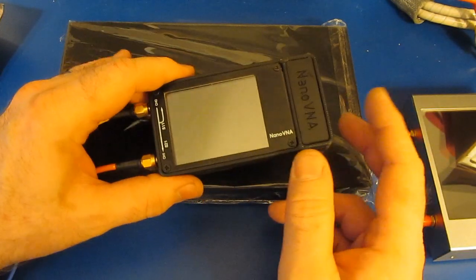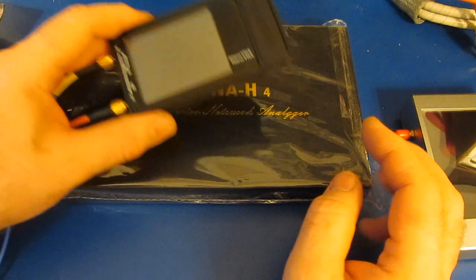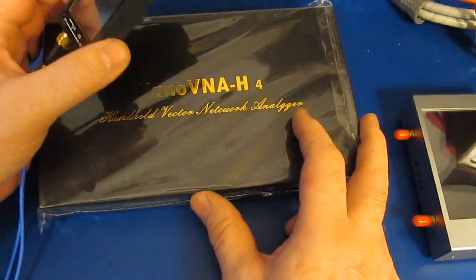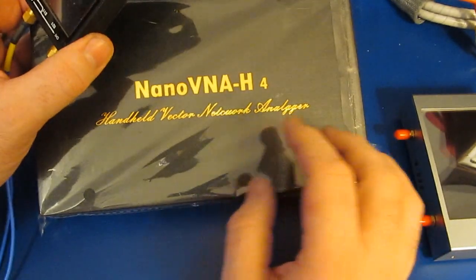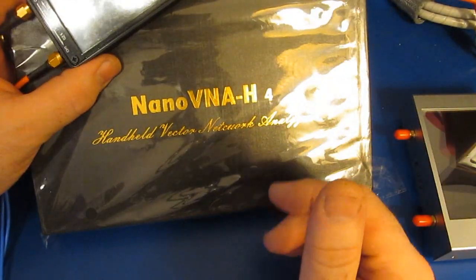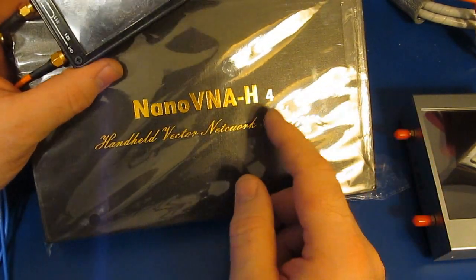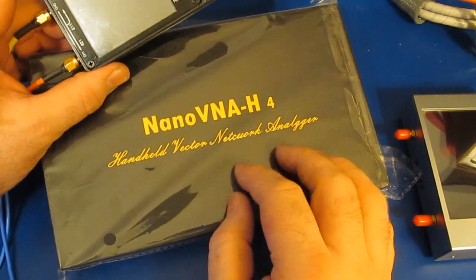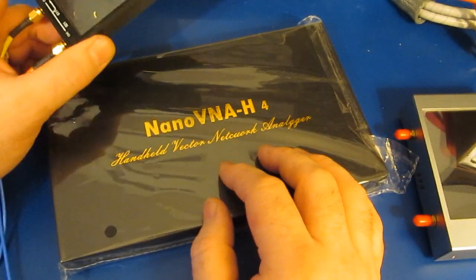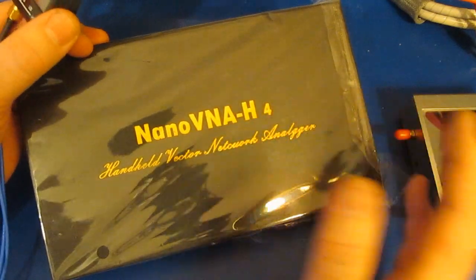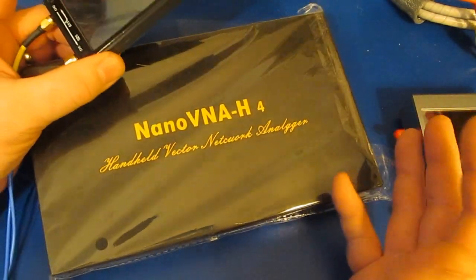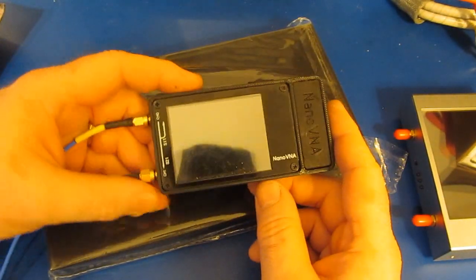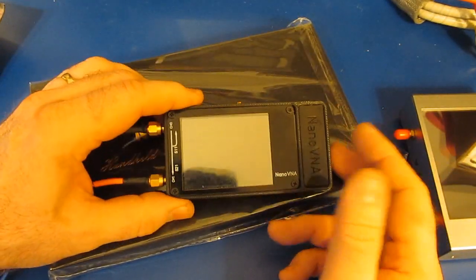Some of the problems that I ran into initially with the firmware for the NanoVNA still exist on the latest firmware for this H4. And unfortunately, I don't see that firmware getting fixed. If you want the 401 data points, then I would say try some of the other firmware that's available. But if you want to try to use this with my software, I would say don't waste your time, because what I find is that the thing can actually output random glitches. And again, that's not a problem with my software, it's a problem with the firmware in this, and it's a problem that's been solved with the original Nano, well over 2 years ago.